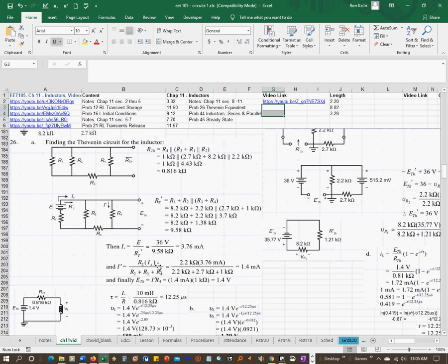So it's the resistor in the other leg, which is R2, times I sub S, the current coming into the node, all divided by R2 plus R3 plus R4. The reason why is because you have R2 in this branch, and in the other branch you have R3 and R4 in series, which is these two added together.